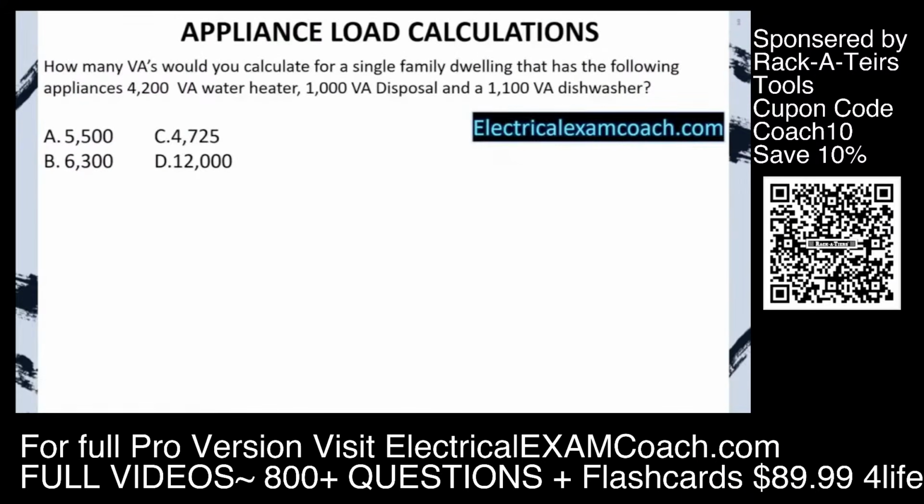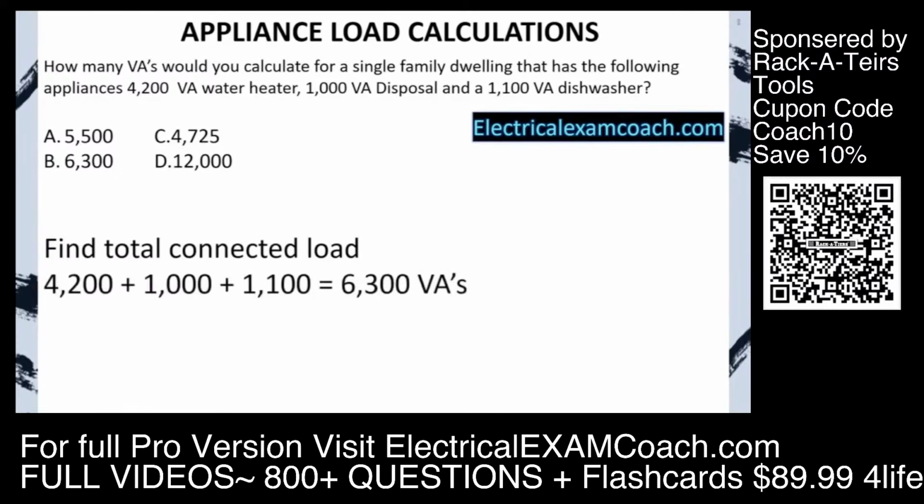How many VAs would you calculate for a single family dwelling that has the following appliances: a 4,200 VA water heater, a 1,000 VA disposal, and an 1,100 VA dishwasher? First, we're going to find the total connected load. We total all that up, it equals 6,300 VAs.